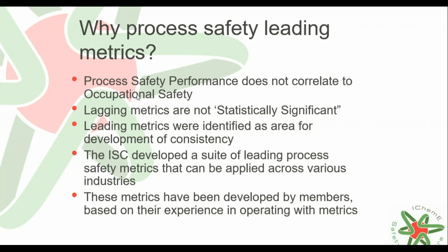Thank you, Steve. There is a question about whether we know what percentage of PSVs examined had defects or faulty installations. Oh, okay. So is that for a plant that's been in operation, or is that a new install? I guess there's going to be a range of answers. So the requirement to set your inspection interval for your PSVs is essentially defined by the performance. And there are some guidances in the PSV codes with regards to what type of defects will allow you to extend the interval or reduce the interval. So that interval I put down as a range, something between 1 and 5 years.